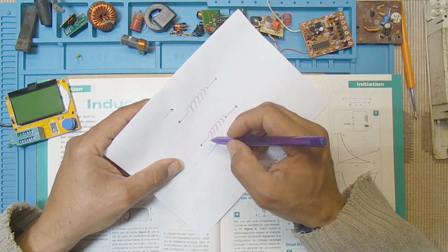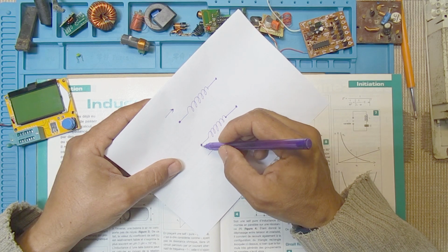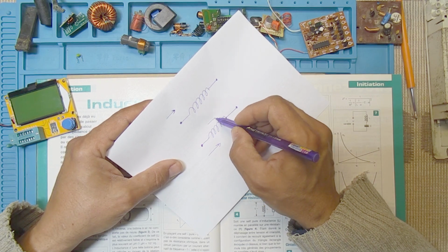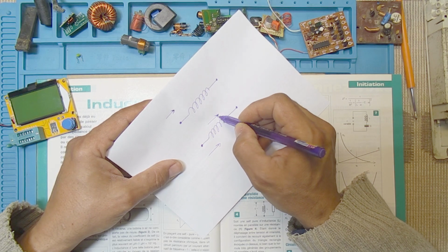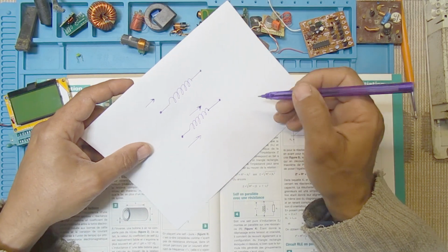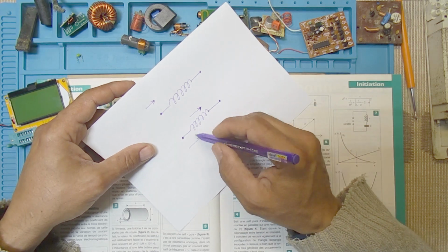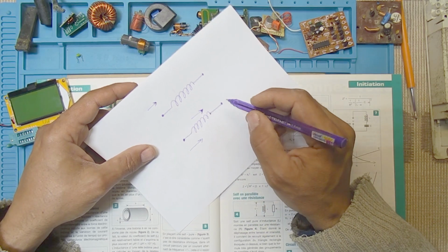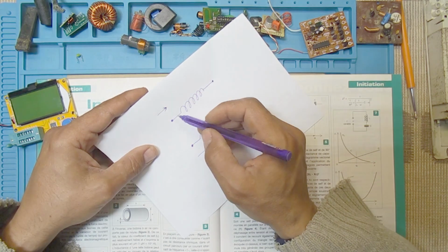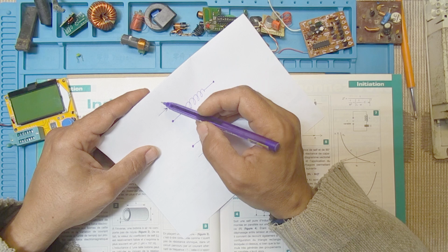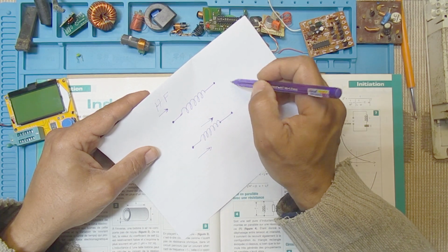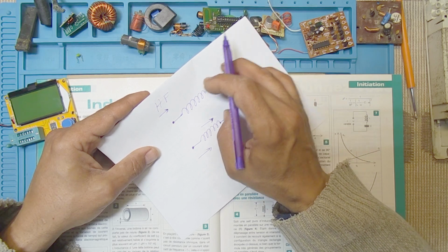And if we power off the source here, it will try to continue the current in this sense. This characteristic is used in the buck converter, the DC to DC converter. And in this part it is used as a choke. It will block the high frequency from getting into the circuit or going out from the circuit.